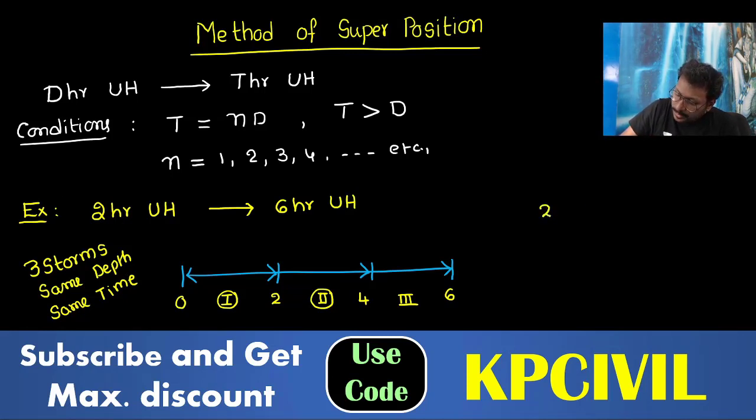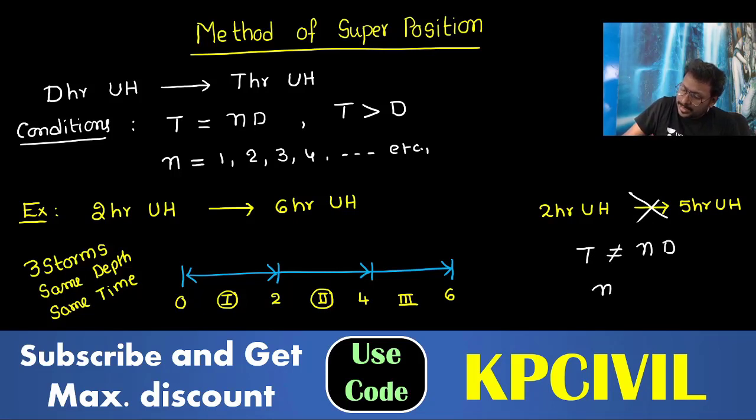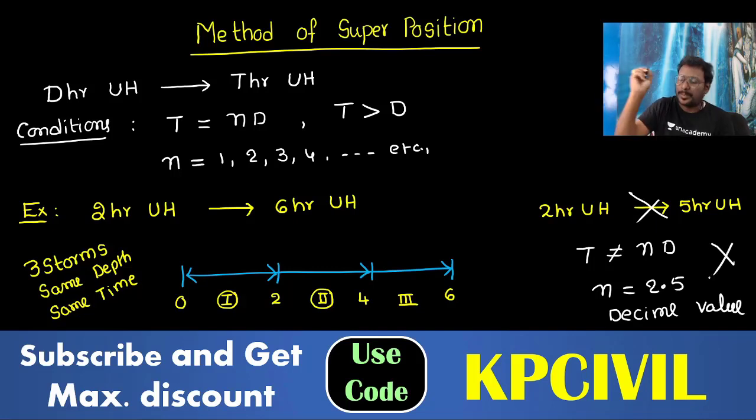For example, you have been provided with a 2-hour UH and you want to determine a 5-hour UH. Will you apply the method of superposition? Not possible, so it is not applicable. Why? T is not equal to ND; N is 2.5, a decimal value. N must be an integer, not a decimal value. Then only can you apply the method of superposition.